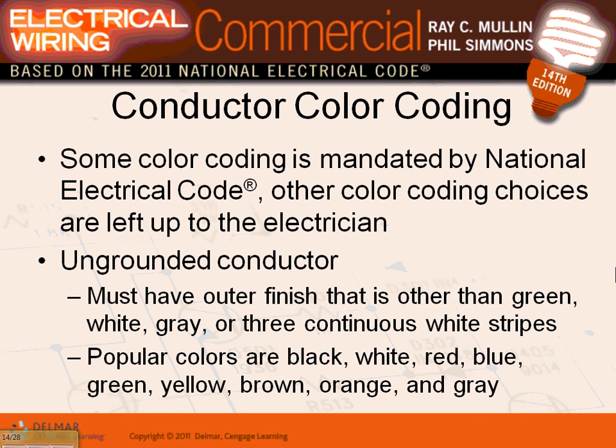And you have the yellow, brown, orange, plus the gray is your 480/277. Any questions, guys? One common, very important thing: do I need the phases of two voltage systems to be identified? Yes, by code, the branch circuits and the feeders at every panel have to be identified by phase and by neutral, if you have two voltage systems coming to the building. If you don't, then the only thing that needs to be identified is the equivalent grounded conductor, green or bare, and the grounded conductor, aka the neutral, has to be in white or gray. Any comment, guys, about identifying the neutral?